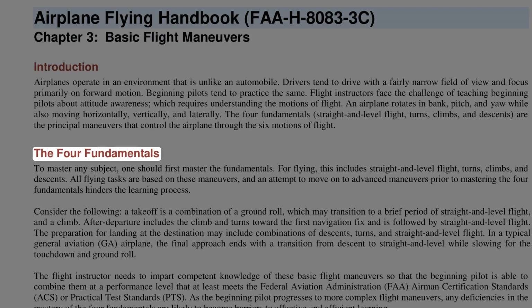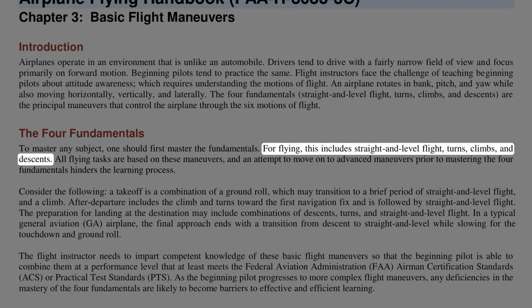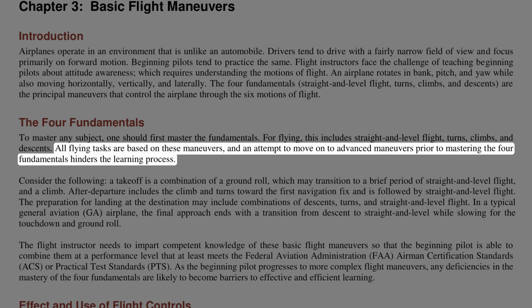The four fundamentals. To master any subject, one should first master the fundamentals. For flying, this includes straight and level flight, turns, climbs, and descents. All flying tasks are based on these maneuvers, and an attempt to move on to advanced maneuvers prior to mastering the four fundamentals hinders the learning process.